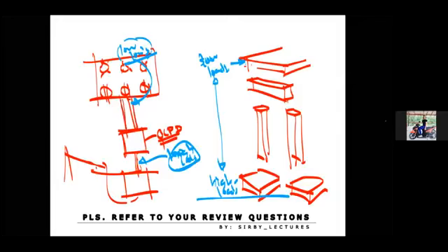Or I'd rather say that we have a wire going to the convenience outlet, and then another wire feeding the lighting outlets. So low loads as compared to the loads right here. So that's why we size this wire bigger, or the size of the wire is bigger here as compared to the wires on this side.